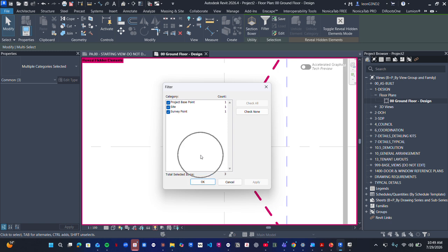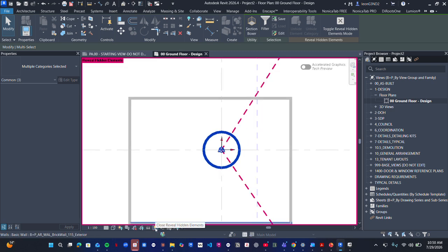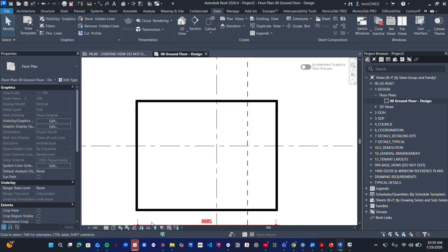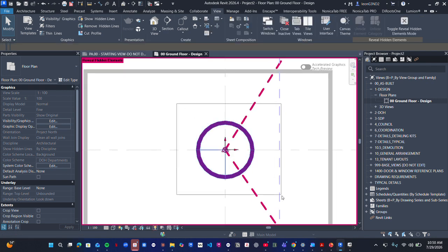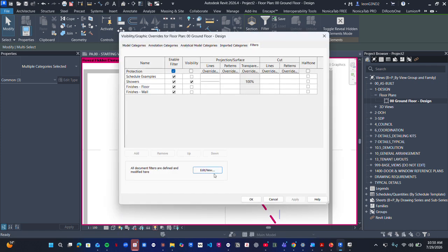The principle behind this is that when multiple disciplines are linking models together, for example architecture, structure, and civil, these shared coordinates are what keep everyone's model aligned in the same location. That is the relevance of this. It tends to come into play specifically when you are doing worksharing. I'll select these and unhide them so they show.